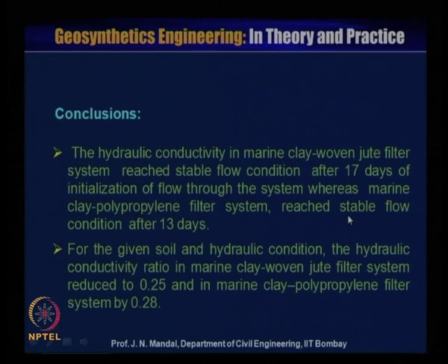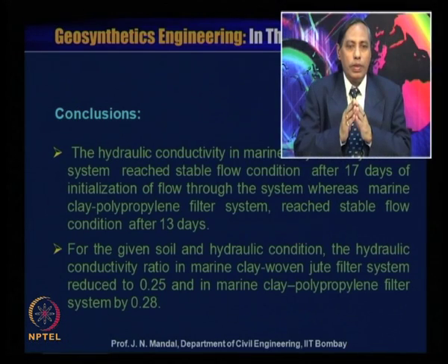So, I am drawing some conclusions. Hydraulic conductivity in the marine clay oven jute filter system reached stable flow condition after 17 days of initialization of flow through the system, whereas the marine clay polypropylene filter system reached stable flow condition after 13 days.